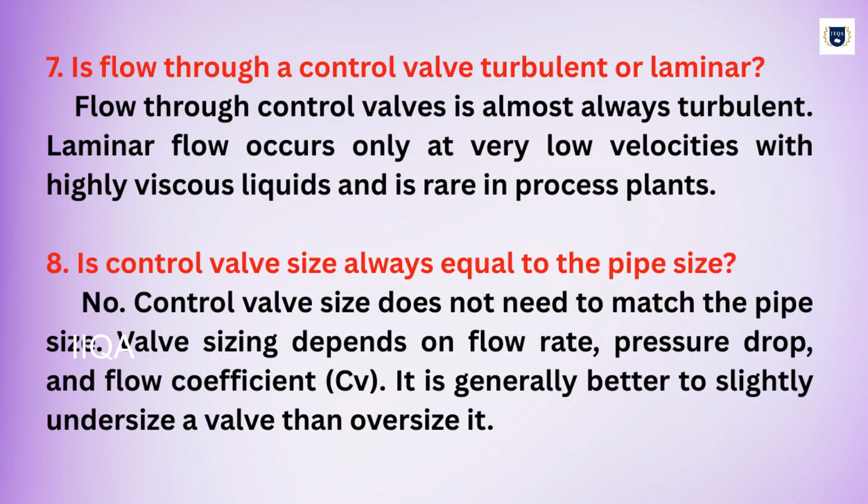Is control valve size always equal to the pipe size? No. Control valve size does not need to match the pipe size. Valve sizing depends on flow rate, pressure drop, and flow coefficient CV. It is generally better to slightly undersize a valve than oversize it.